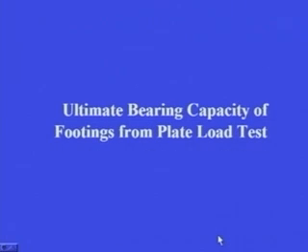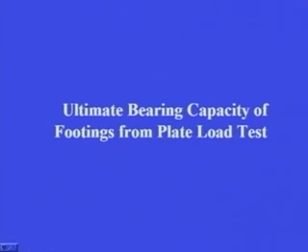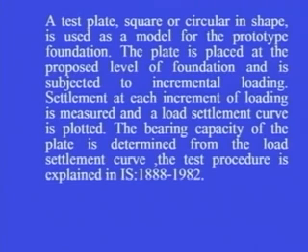Another test which we normally use in the case of granular soil, which is most suitable for granular soil, is the plate load test, and from the plate load test data we can find out ultimate bearing capacity of footings. Now, in the plate load test, a test plate, square or circular in shape, is used as a model for the prototype foundation.